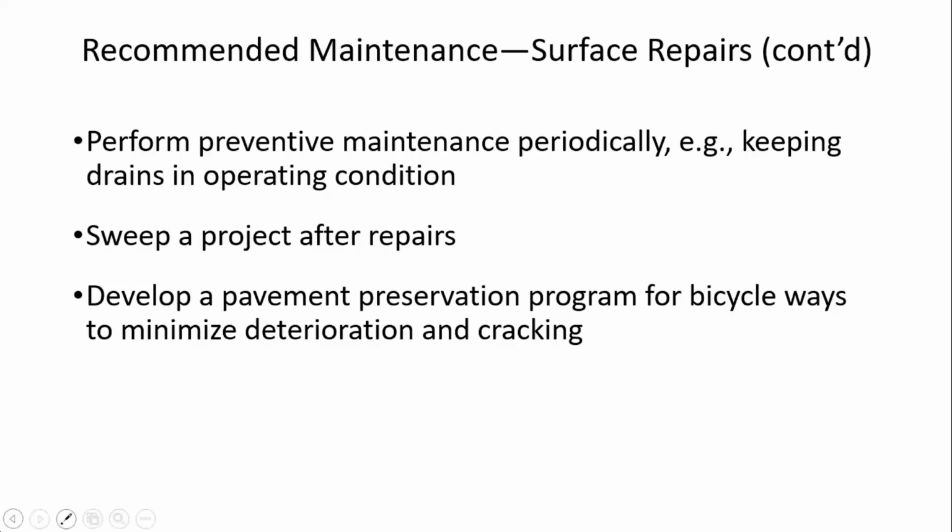Perform preventive maintenance periodically, keeping drains in operating condition. After a project, maybe one that has made some repair to a roadway, sweep to make sure the loose material is removed from the travel way. And then think about a pavement preservation program for bike facilities that minimizes deterioration and cracking.